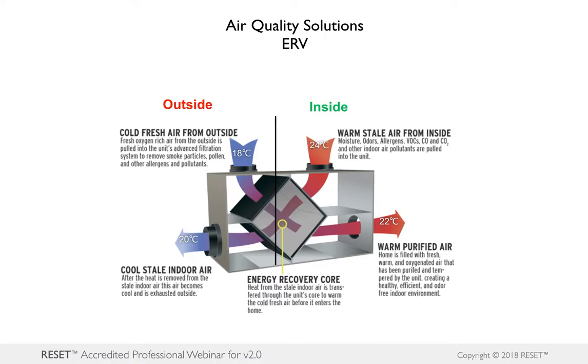So I just mentioned it, ERV. Again, it stands for Energy Recovery Ventilation, or ventilator, depending on what tense and what circumstance you're talking about. But ERV is the energy recovery process of exchanging the energy contained in air that is normally exhausted, and instead you're using it, you're treating it, preconditioning the incoming outdoor ventilation air.